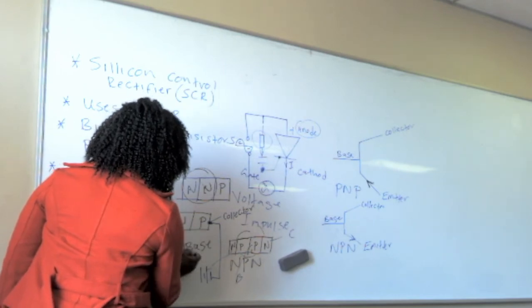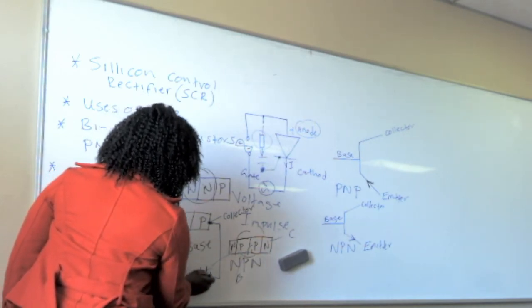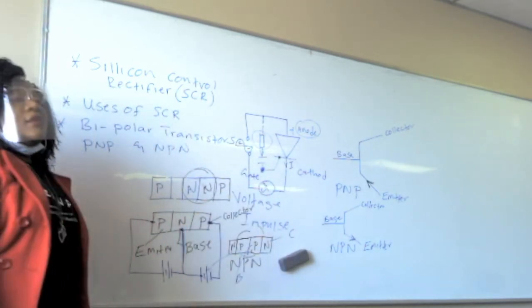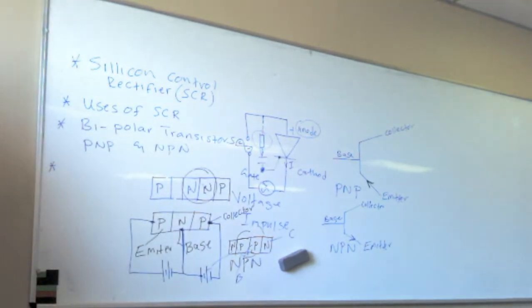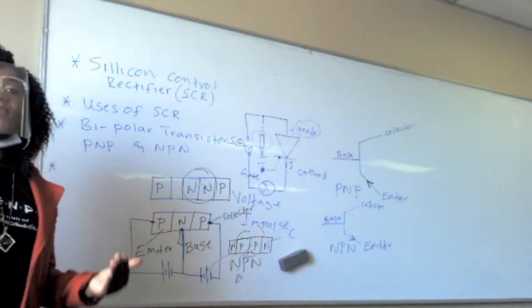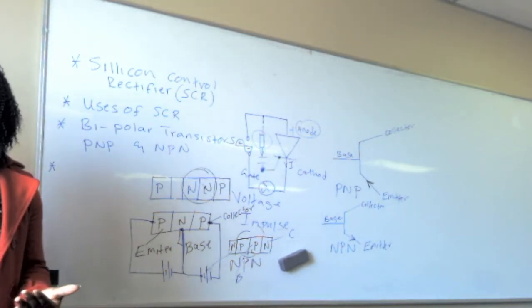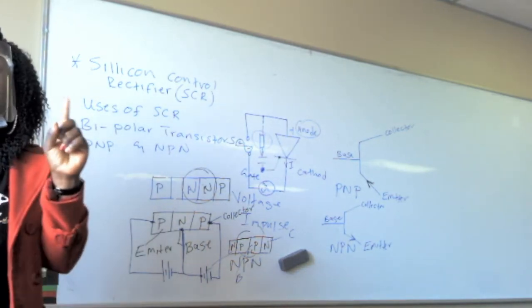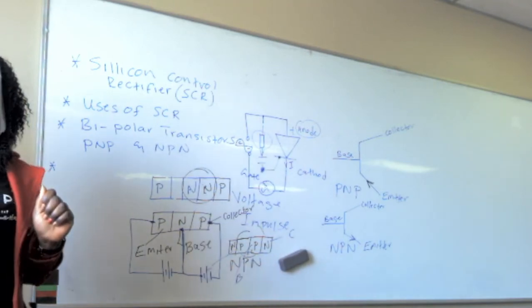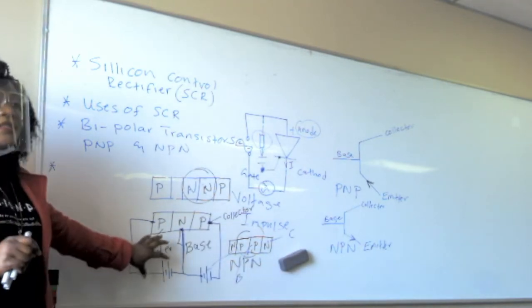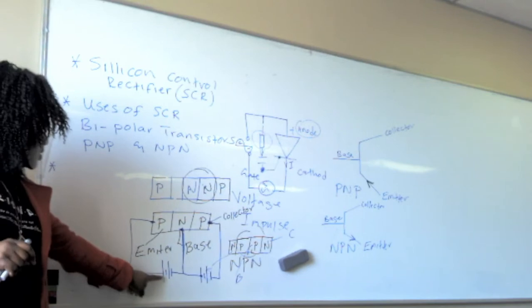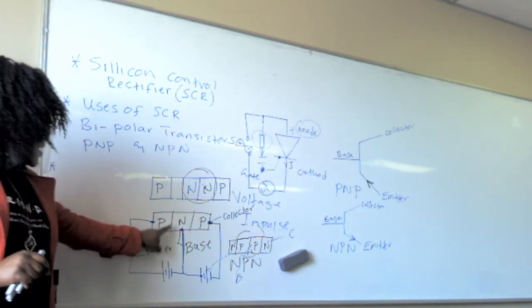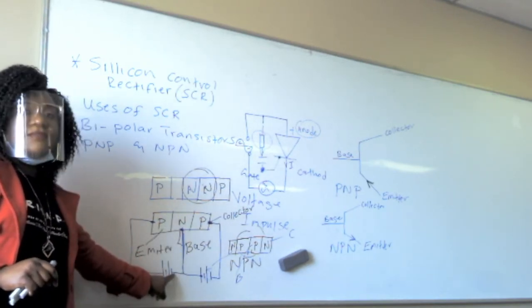Then the negative wire of the base is connected here. Transistors must have two supplies because we're saying they control the flow of current. So one side must be in reverse bias. The one that is in forward bias is the emitter side, because that is the arrow direction. You see here they were connected on the emitter side. Positive to positive. Negative to negative.